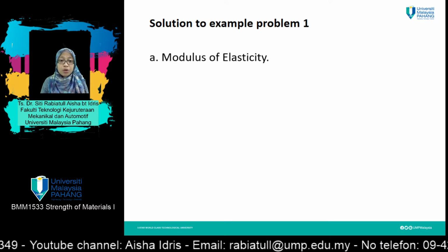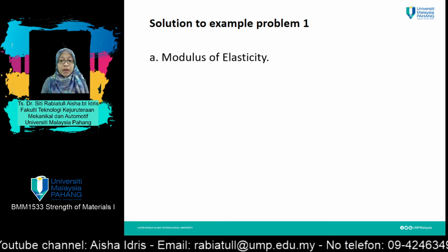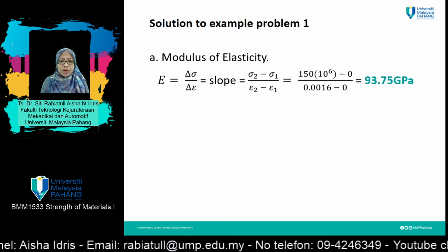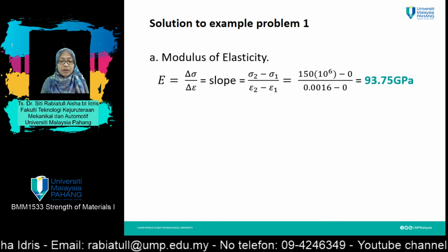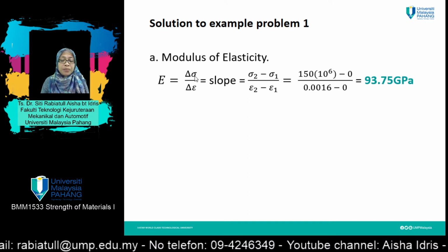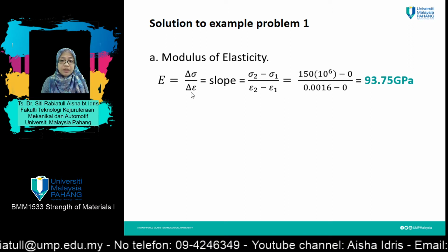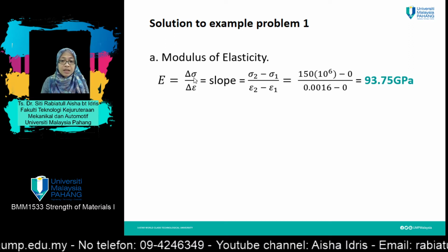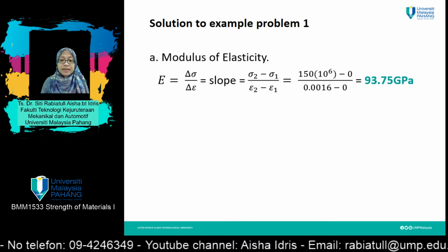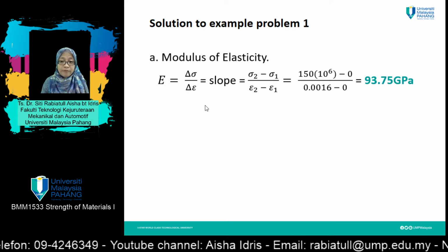A, the question asks you to find the value of the modulus of elasticity. If you still remember, Young's modulus equals sigma divided by epsilon. Sigma is stress, epsilon is strain, which you can get from the slope of the graph.